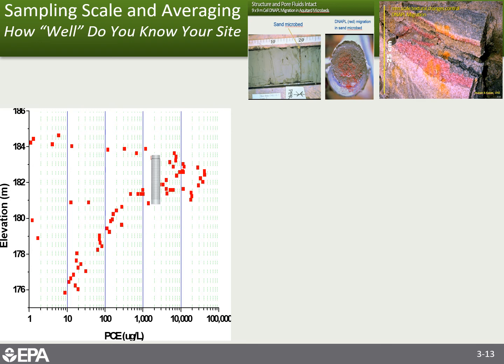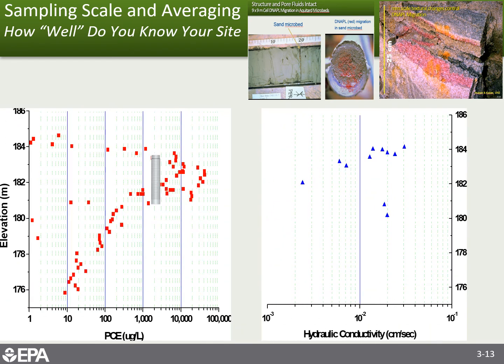So how can that be? As Seth questioned himself, was the tool creating mass? Well, of course not. So what the tool provides is a measure of hydraulic conductivity. And what you see in many of these wells, and why some of my colleagues over the years have joked that monitoring wells are holes in the ground that lie, not necessarily true, but you need to be very careful in understanding the type of data and information that you're getting from a monitoring well, particularly long screen wells.